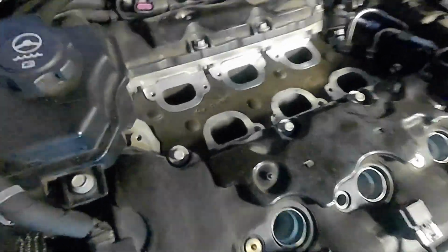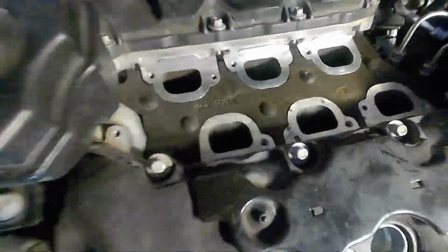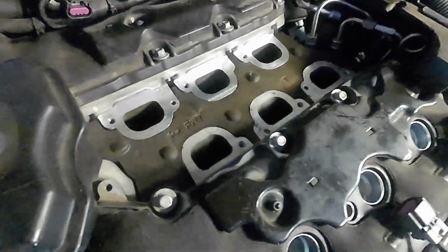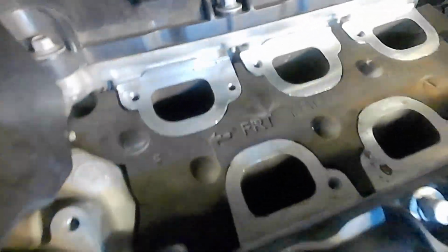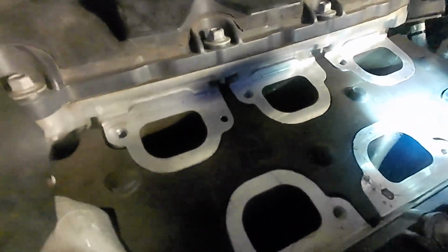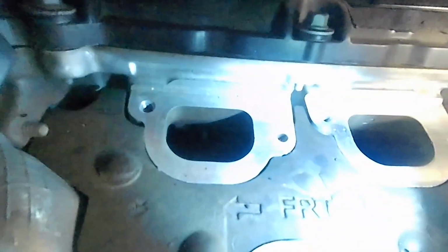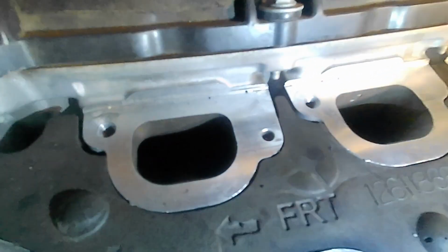I'm going to show you how to clean the intake chambers. Those are the ones showing us a code for misfire. Even after replacing the ignition coils and the spark plugs, we still get the misfire on this chamber in particular. So I'm going to go ahead and show you guys how to clean it.